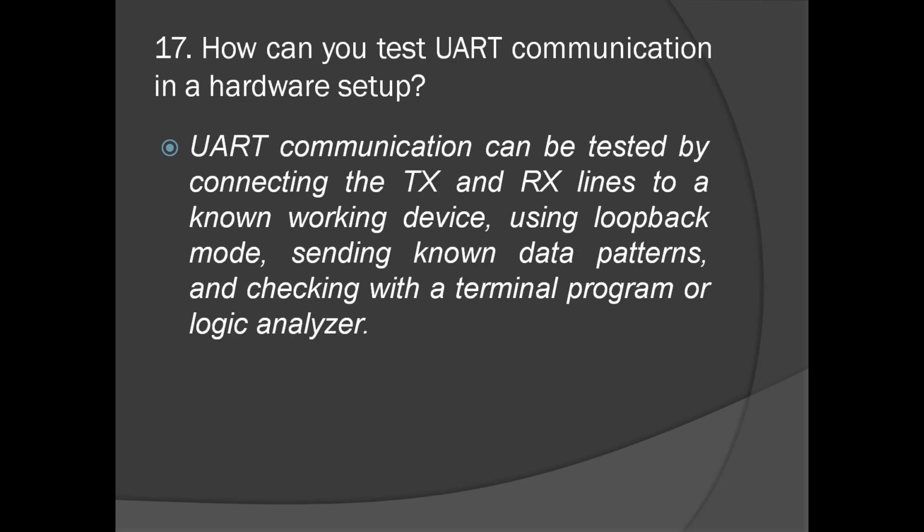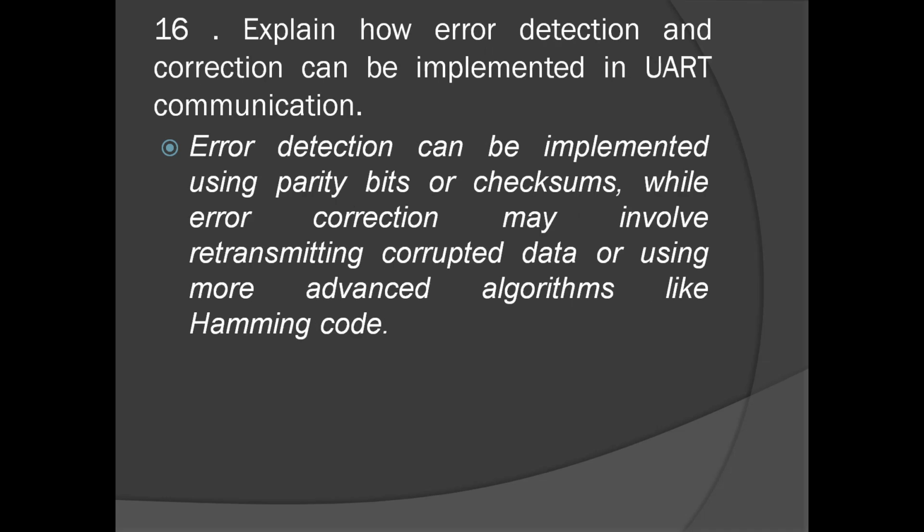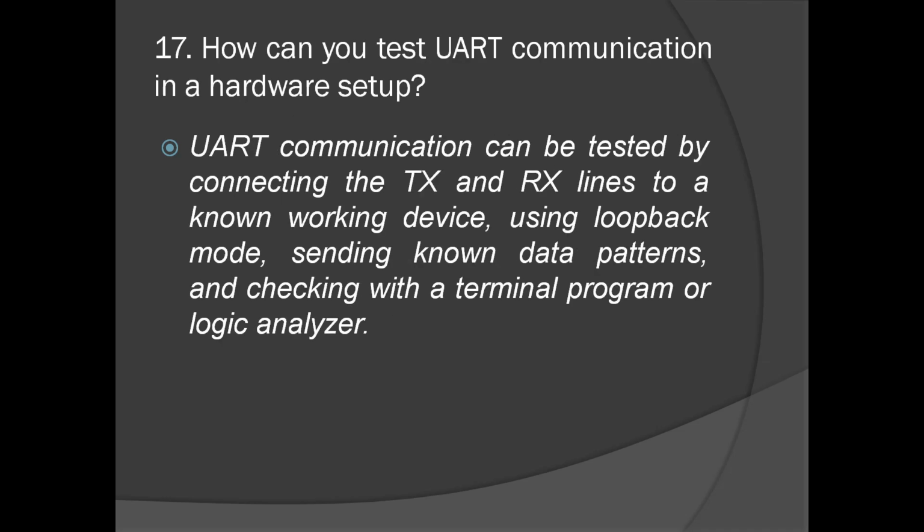Coming to this, UART communication can be tested by connecting the TX and RX lines to a known working device or using loopback mode, sending known data patterns and checking with a terminal program or logic analyzer. In a UART module you have transmitter and receiver, TX and RX lines. So, sir, you are saying we have to connect the transmitter and receiver lines to a working device, and check the 8-bit or 10-bit data bit by bit. Yes.